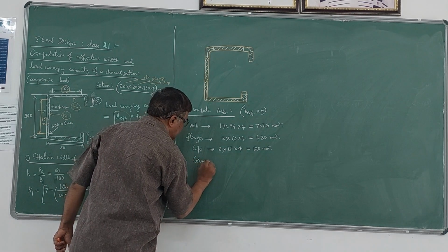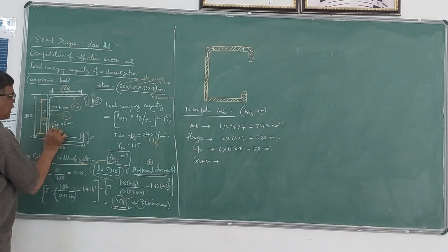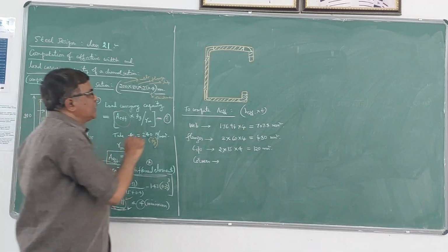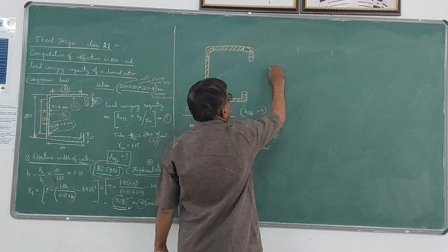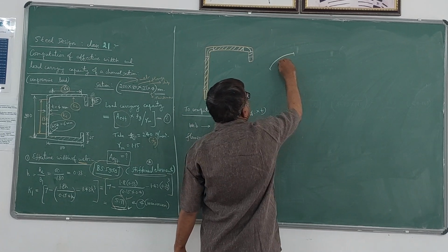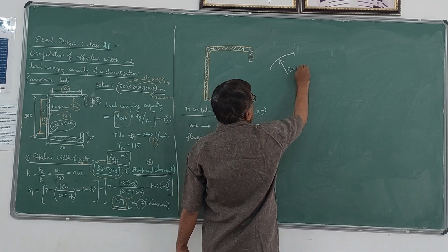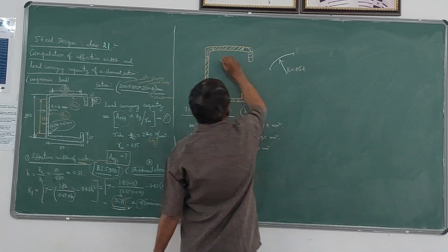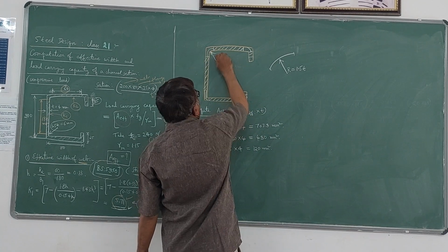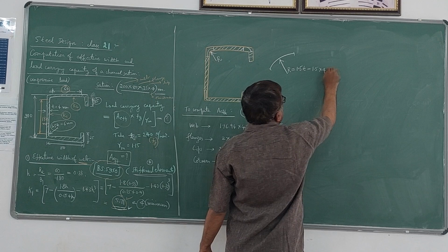Normally at this corner you will be having an arc of a circle like this. So you have to understand here, the center line of the corner. Here, this radius R will be 1.5 times t for this corner, which is 1.5 into 4, 6 mm.